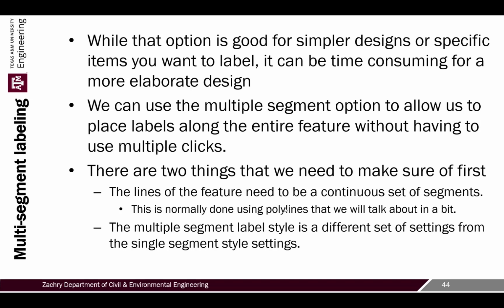The other thing is the multiple segment label style is going to be a different set of settings from the single segment style settings. And you're like, what's the big deal? It actually is the exact same dialog box, but when you switch to multiple, it flips to a different set of styles. And so you want to make sure that you set those, and if you're trying to keep them consistent with your single segment style, to the same style. Otherwise, sometimes you'll end up with things that you don't want.